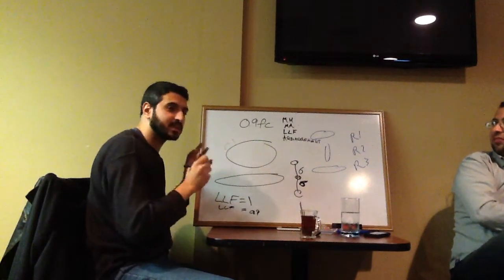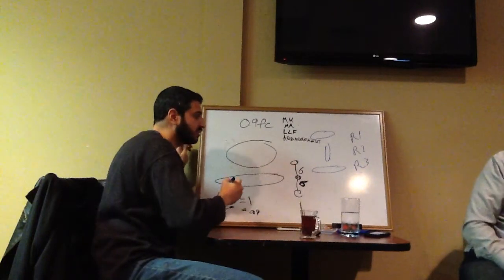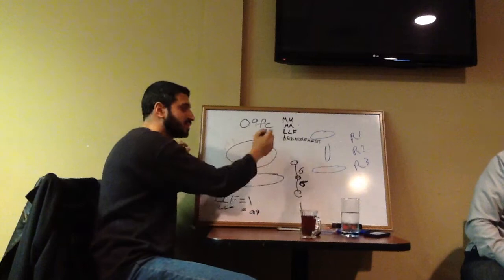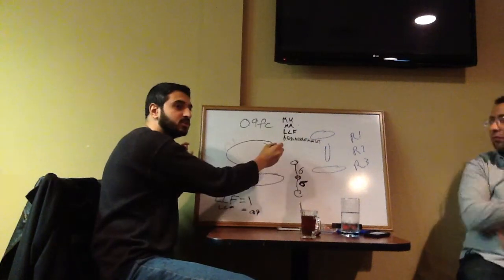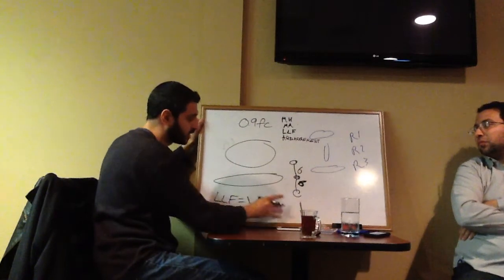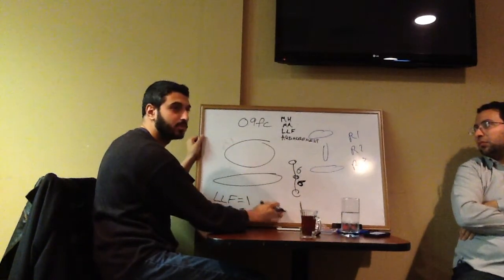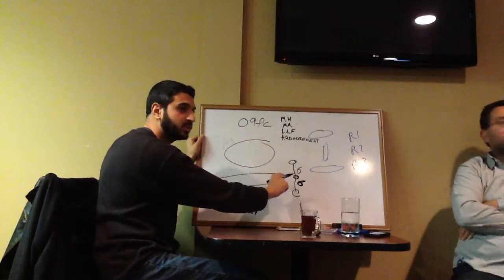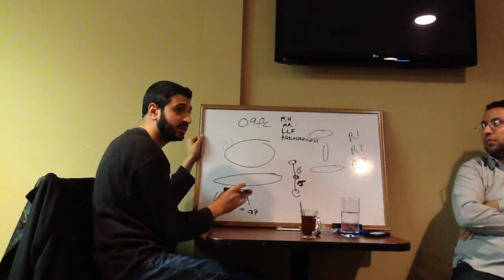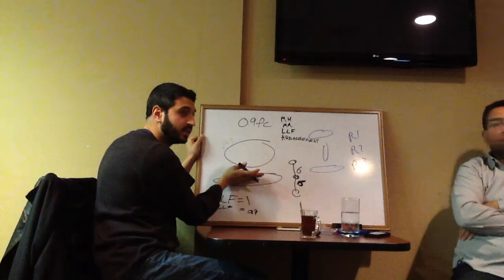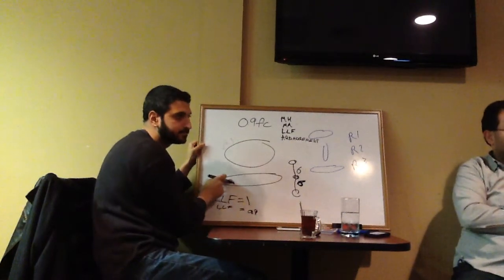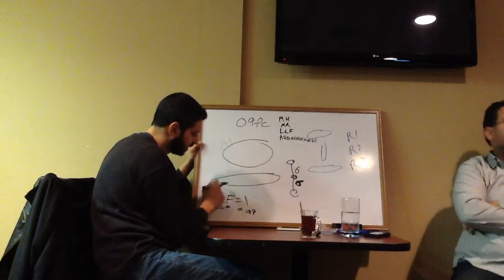It's kind of like a calculator for you. You could either give it the spacing that you want to test out, or you could tell it to figure out the spacing based on the light and the information that you give it. You also have to input the layout type. Remember we said we chose median mounted. Then you have to put the setback, meaning how far the pole is from the road.